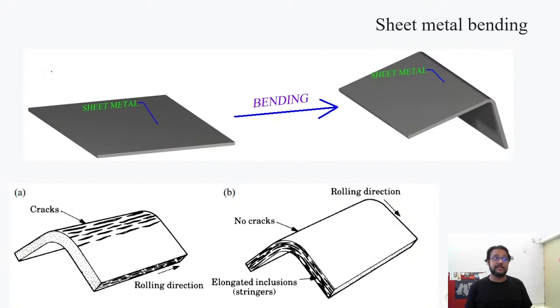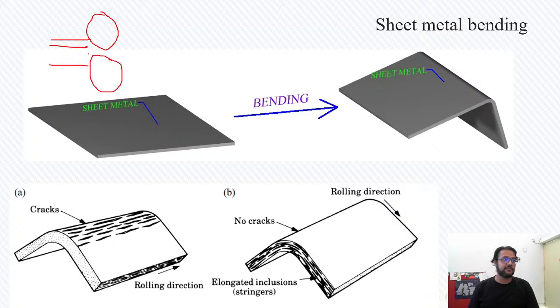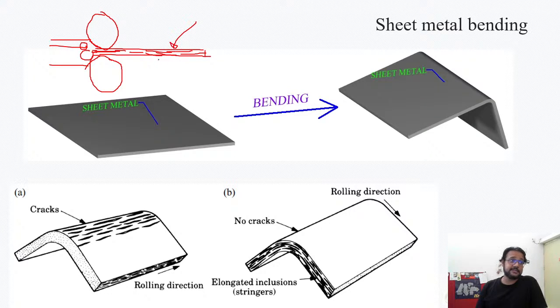So what happens is, how is sheet metal made? We discussed in our prior class, there's some process called rolling, where you would have these two rollers and a thicker sheet of material is passed on from one end and a thinner sheet comes out at the other, right? And because of this kind of an operation, the grains kind of elongate. If there were grains which were much larger, they would elongate because of this operation. If you don't do the recrystallization operations, you would get materials which are not recrystallized, right? So you would get these longer grain structures with some internal stresses that give it strength in a certain direction and hardness along its surfaces.